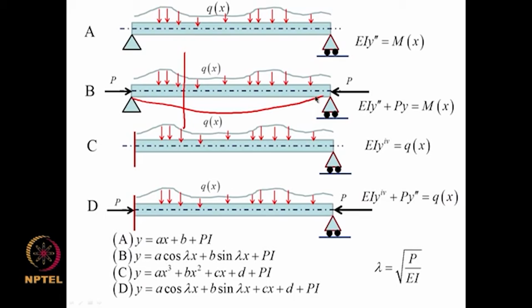So this was our first taste of the issue of nonlinearities, where to find bending moment m of x we use undeformed geometry, whereas to find the contribution from axial loads we use a deformed geometry. So that played a crucial role, and we saw that the presence of an axial load produces a dramatic effect, and some basic notions like the principle of superposition become the first casualty in the treatment of axial loads.